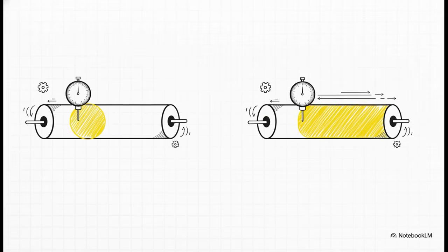Okay, if you guessed that the stationary setup is circular runout and the sweeping setup is total runout, you nailed it. That physical difference, inspecting a 2D slice versus sweeping a 3D surface, is exactly how you need to visualize these two symbols on your drawings. Sweeping the indicator guarantees that every single point on the surface falls within those two perfect imaginary coaxial cylinders.